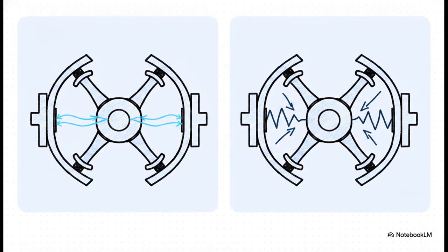Now, as that rotor spins, the magnetic circuit it creates isn't just perfectly uniform. When the rotor pole axis perfectly aligns with the stator coils, we call that the direct axis, or D-axis. The magnetic reluctance here is at its absolute minimum. Conversely, when the rotor is at right angles to the stator coils, it faces the widest part of the air gap. This is the quadrature axis, or Q-axis, and the magnetic reluctance here hits its maximum. This steady-state shifting of magnetic reluctance is the baseline of our machine. But what happens when things go wrong? Let's dive into how the mathematical models dramatically shift over time.